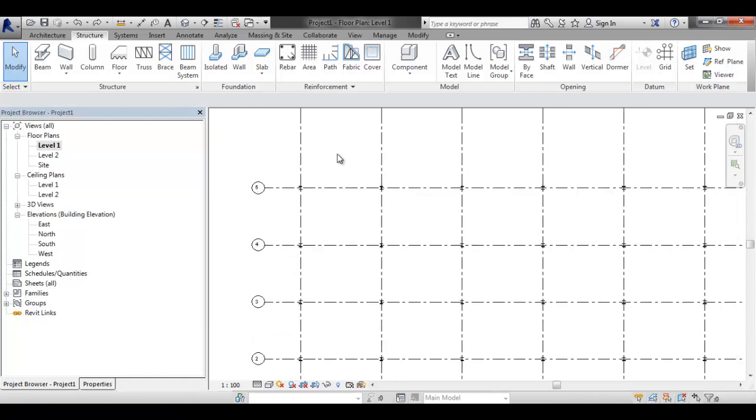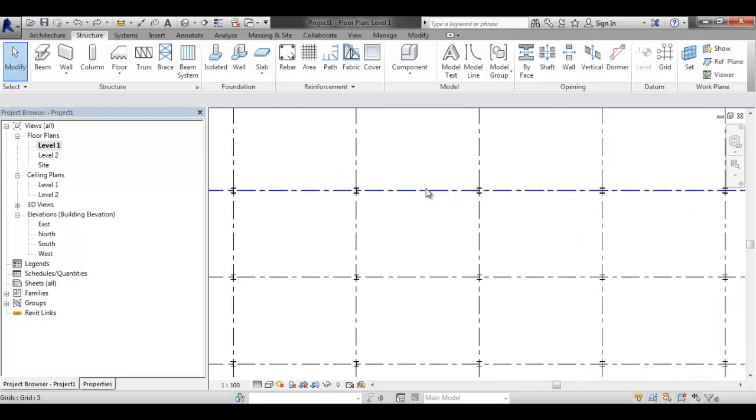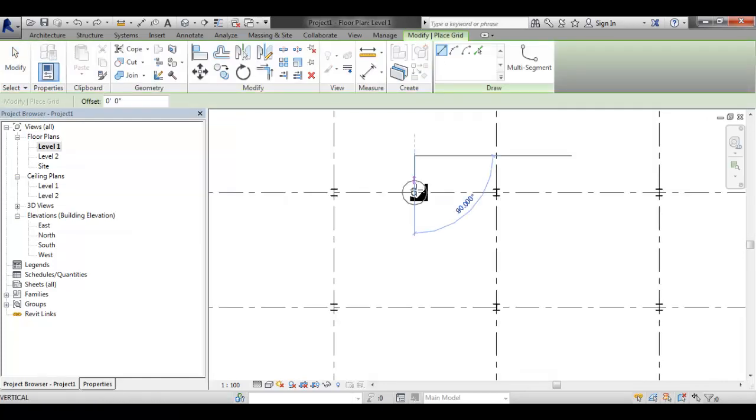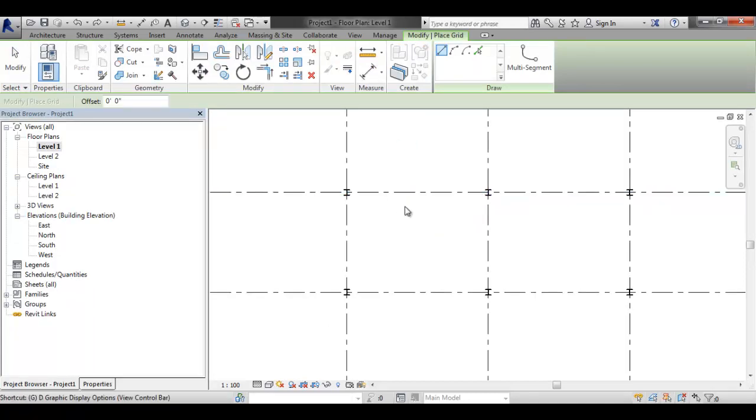Again, the purpose of the grid, right, is for construction documents. So to move it off the grid, let's say I had a condition where I needed another column. The structural engineer says, whoops, you've got a heavy load coming in right there. You need another column right in the middle to pick up that load. I would do a one-off grid here, right?